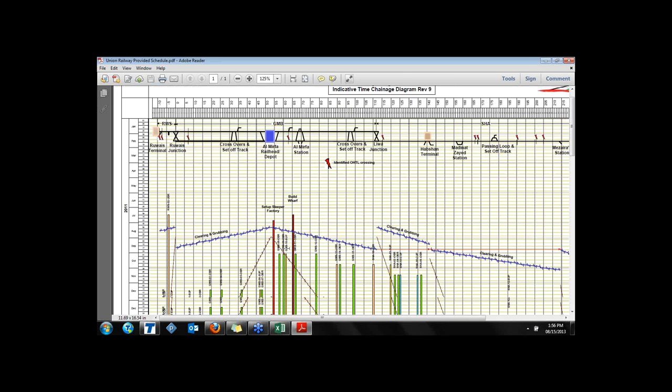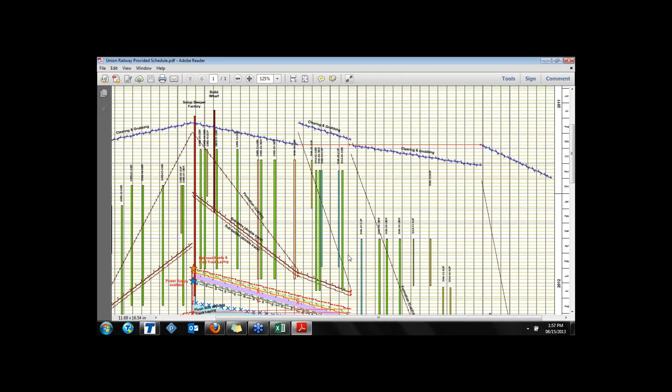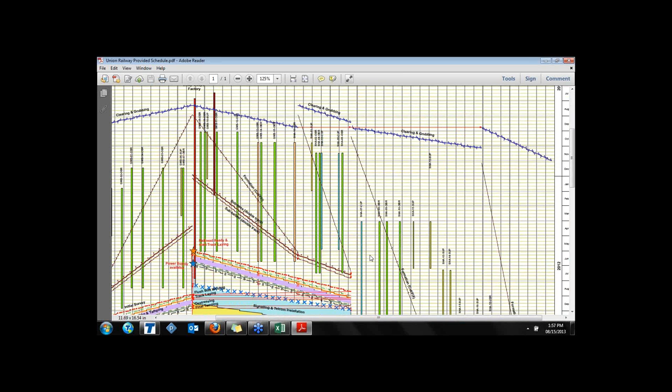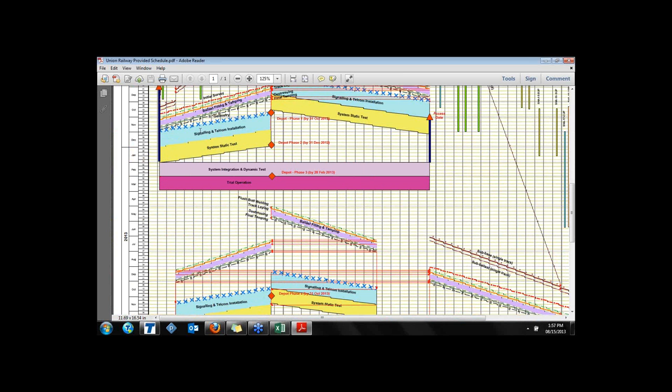They prepared their schedule in TILOS in detail with the combination of Primavera, so they submitted the project. And you don't have to show only linear activities, you can show non-linear works as well, such as here signaling and telecom installation. This is having a lag here, please see here, and this is taking over 2 months, so you will be following your non-linear works as well with your constraints and your milestones.